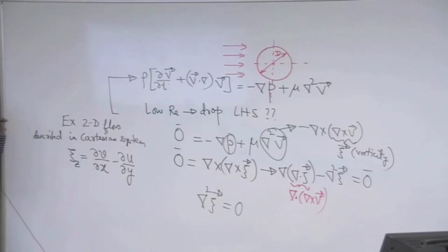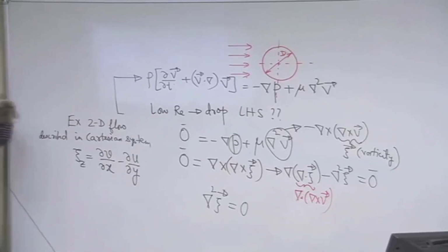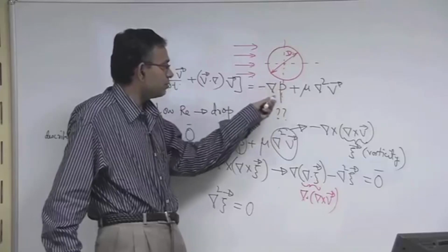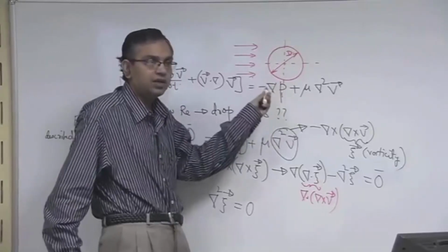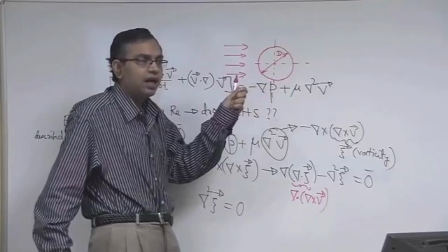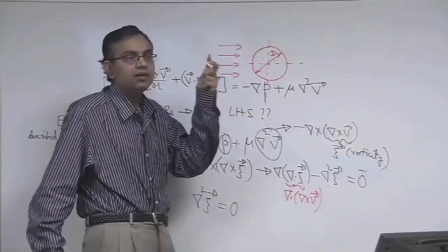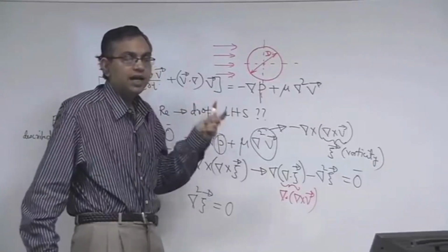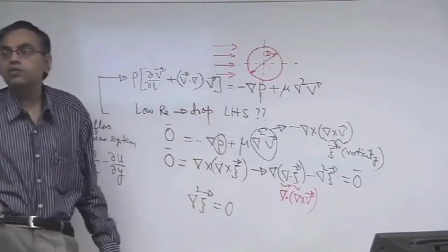Now, for a 2-dimensional flow, we had said that by eliminating the pressure term, we are not having an explicit linkage of the continuity and the momentum equations, but there has to be some reference to the continuity equation.